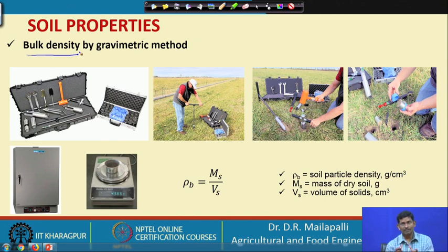Since it is bulk, this is bulk density. Similarly, soil has this physical property called bulk density. If you put soil in a glass, knowing the soil mass weight divided by glass volume will give the bulk density. But in the field, how to estimate this?